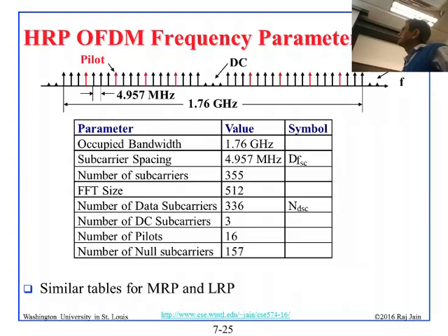These 3 in the middle are really direct current, which means that they don't have any frequency as such, right? But those are basically gaps, which are used for frequency synchronization of some kind. I've seen DC subcarriers in the center in all the other standards that we'll see. So these 3 in the center are the DC subcarriers.